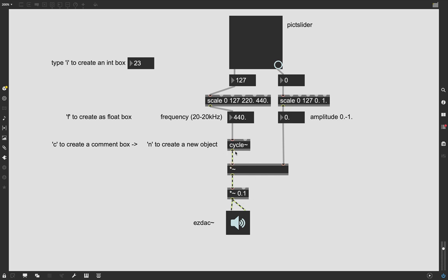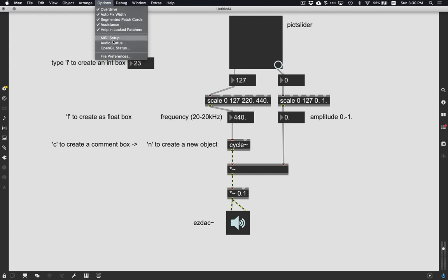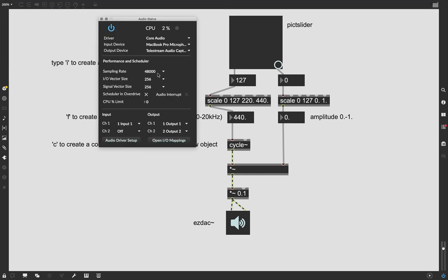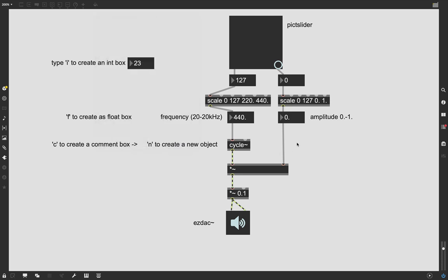The reason why that happens is in the audio domain, we're processing new samples to listen to 48,000 times a second. And that's determined by our sample rate right here. This is how many times a second we have to generate a new output sample. Whereas in the control rate, we're only updating this value when we enter it. So if I type in 0.5, it updates that value when I press return.